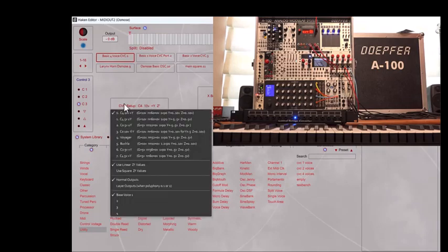If I click on CVC Setup, you'll see there are 7 default voltage options that have been predefined for various different kinds of modular devices and modular synths. One would be 10 volts, gate, note 60 equals 0 volts. That's basically MIDI note 60 equals 0 volts and a 1 volt per octave output. Y, aftertouch equals 0 to 10 volts, Z equals 0 to 10 volts. And you have a lot of different options for connecting up to different things like Voyagers, Buchla, and other configurations that have a mix of 5 volts and 10 volts.